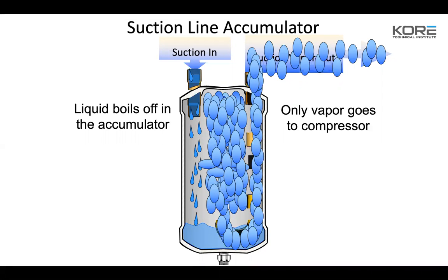But then the superheat at your compressor, you still want to take that, because that's going to tell you how much liquid is still coming back to your compressor. And if you're dropping below 20 degrees superheat at your compressor, it's coming back too rich. Now, I know every rack guy on this PowerPoint is saying, wait, we can go below 20. Yes, on a rack, when you have multiple compressors and a big suction header, that is correct. But for single systems and for most of the systems out there, if you're getting close to 20, you're flirting with it.